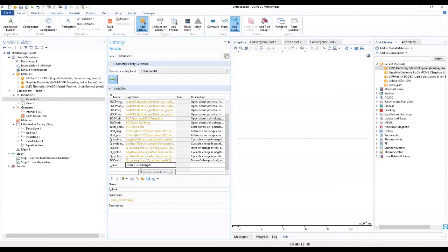Let's see. So this internally defined variable will define the constant current that will completely charge or discharge the battery in an hour. So it's defined by the initial cell charge distribution node, which I will add as we move on. As we move on, I'll add the initial cell charge distribution node to it, and it will be defined appropriately.